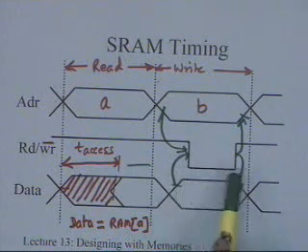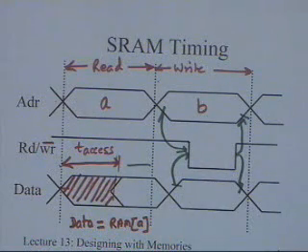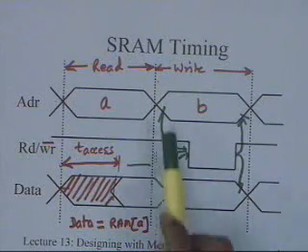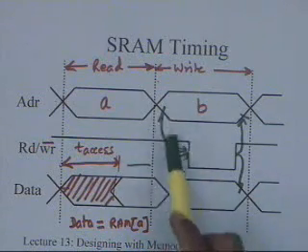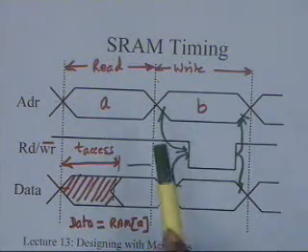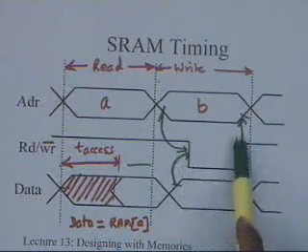That is, during the whole time when your write signal is active, it is low, your address and data should not change. This requirement is not there for the read, but this is a very, very stringent requirement for write. Of course, how much timing distance should be there could vary from device to device, but almost all devices require that.